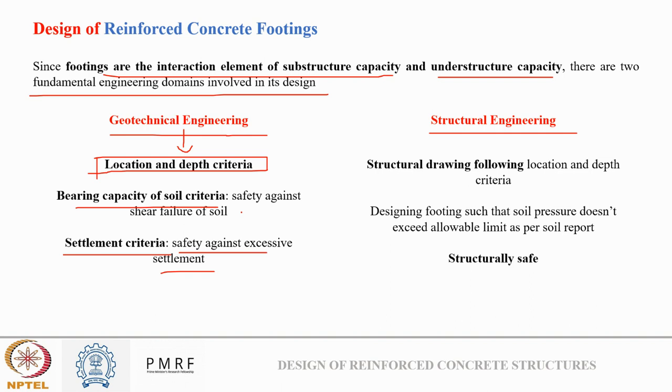So this bearing capacity is very important for us when we are designing a structure. We need to know how much load a soil can bear. Accordingly we need to provide the dimension of our footing. Okay, we'll see later on how it comes into play. So just remember, from geotechnical engineering we get the bearing capacity of the soil, varying with depth or at a particular region.